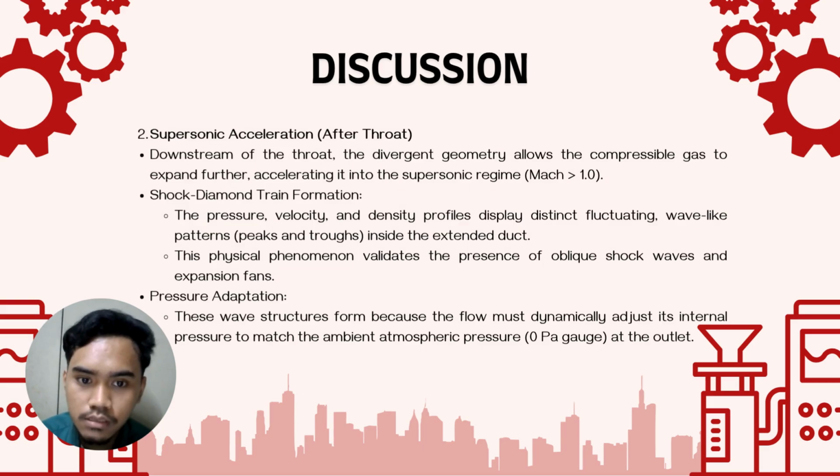The pressure, velocity, and density profiles display a distinct fluctuating wave-like pattern, which is like the diamond one inside the extended duct. This physical phenomenon validates the presence of the oblique shock wave and expansion fan. Okay, so at the end of the extended duct, we can see the pressure adaptation actually. This wave structure forms because the flow must dynamically adjust the internal pressure to match the ambient atmospheric pressure, which is as we said earlier in the boundary condition, the zero Pascal gauge at the outlet.